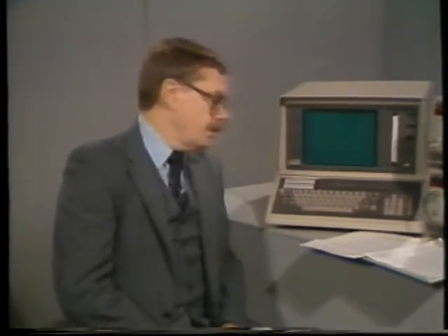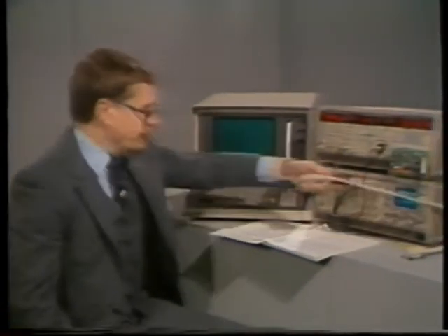Fundamentally, we're talking about an interconnection standard for small to medium-sized instrumentation systems. IEEE 488 is a mechanical standard, an electrical and functional standard, but not an operational standard. It defines nothing about the operation of the devices on the bus other than their very fundamental interaction with the interface itself. Here's a standard GPIB cable with connectors.